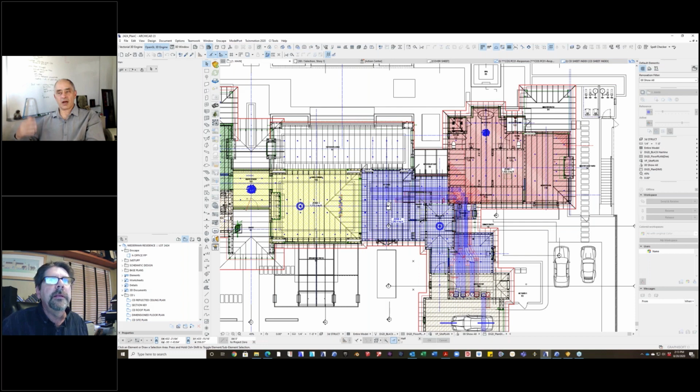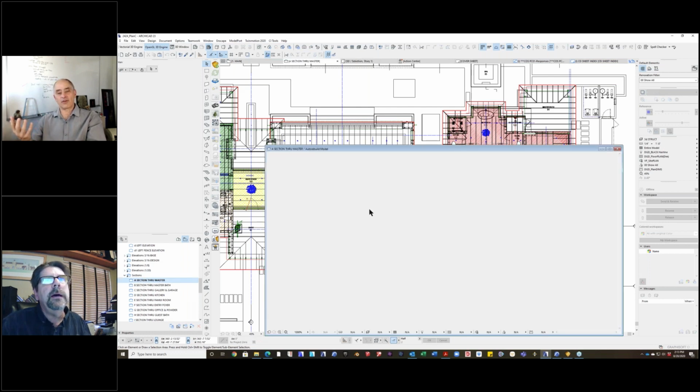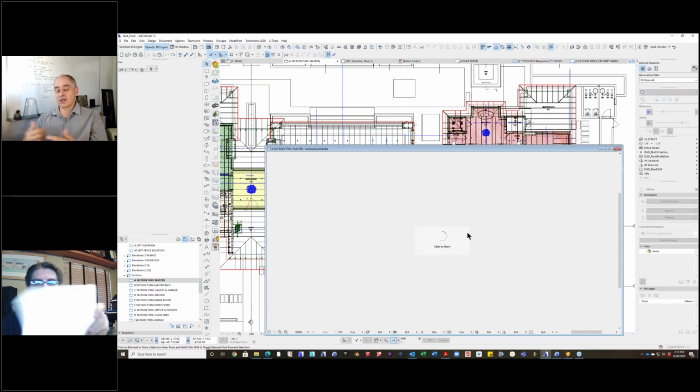All right, so you're basically cutting a section saying, hey, I need support here. You're drawing it just like you might in 2D to say, here's the shape that I want. You're doing it with the fill tool, or you draw with lines and then create a fill from that. Now that fill, which looks okay in section, is purely 2D. You copy and paste it into the profile manager, and it instantly creates a 3D element that can be used in 3D. So you don't start out your template with a whole bunch of these. You just create them in the project as you need them.